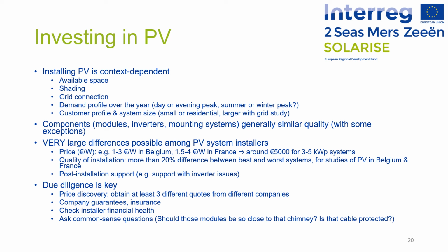With this, due diligence is key, that you need to have price discovery. So it is recommended to obtain at least 3 different quotes from different companies, that you also investigate the company guarantees and insurance that is offered, that you check the installer financial health, and that you ask common sense questions. For example, should those modules be so close to that chimney? Is that cable that I see running over the roof, is that protected?